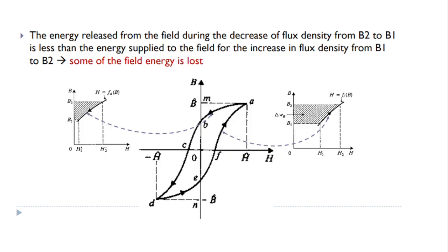So that's basically doing the same thing, explaining what I went through just now. So this first piece you're increasing. So if you're increasing, all this will be the area. And then when you're going back down, when you're decreasing, which means you're decreasing the current, which means you're reducing the strength of the magnetic field, the area bounded will be just this piece on top here. So the losses are due to hysteresis, not the drift.